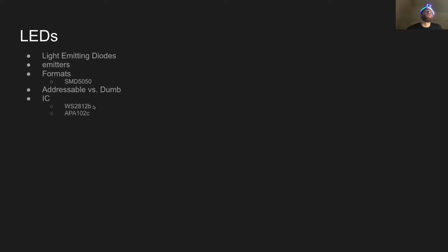So 2 IC types to recognize and remember. These are the 2 most supported, most widely used, most conventionally found by hobbyists. They're good options to look for. The first is called WS2812B. It just rolls off the tongue, doesn't it? So WS stands for World Semi, which is, I think, a Taiwanese manufacturing company, and 2812B is sort of the part identifier.